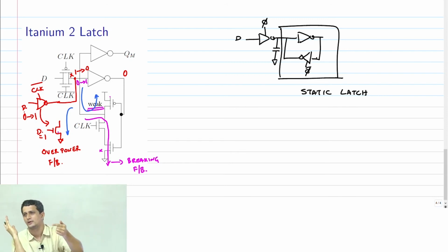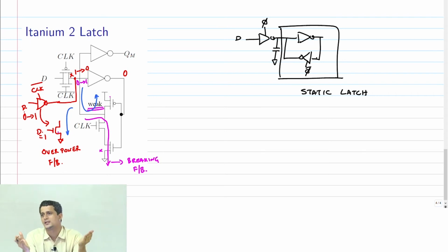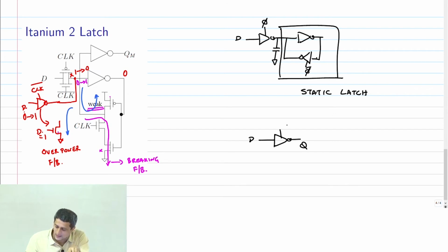So there is something driving it. So if you look at very high clock speeds of the order of gigahertz, then the data has to be held only for 1 nanosecond. Right? And technically it is possible to do this with a reasonable capacitance on chip. Right? And therefore you can simply use a tri-state inverter as a dynamic latch. Fine. Okay?